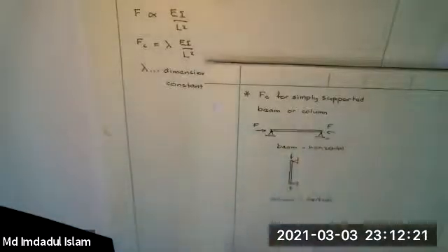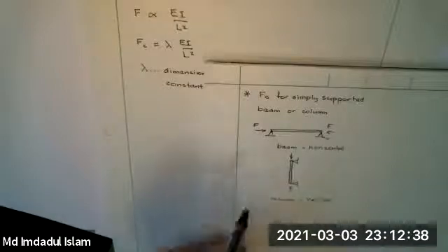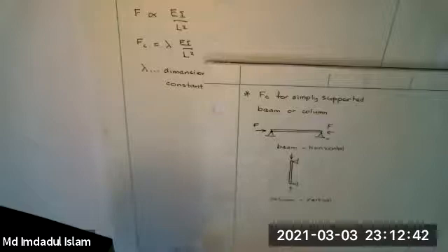Okay. So you have two competing mechanisms. For metals, which yield, the competing mechanisms are yielding and buckling. And depending on the relative length, you'll get one or the other, and that's a decision we'll have to make. In the short term, we'll just try and figure out buckling, and later on we'll come back and think about yielding.